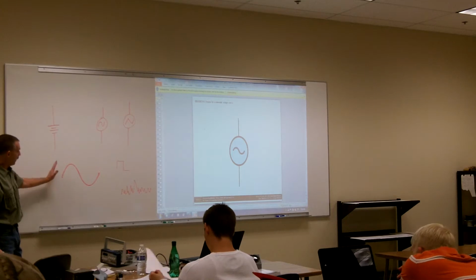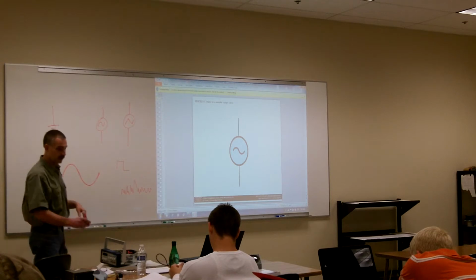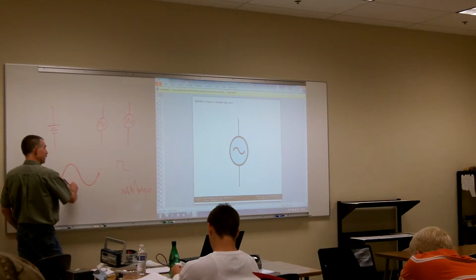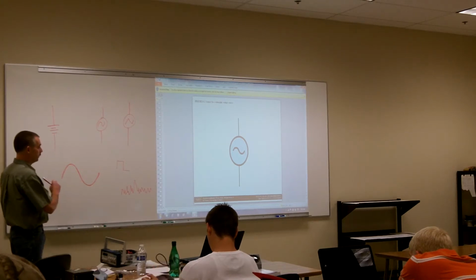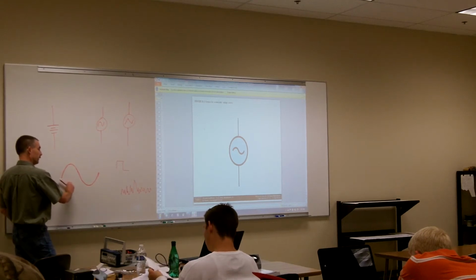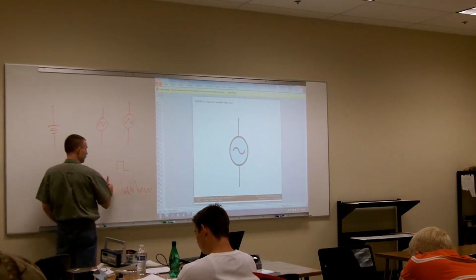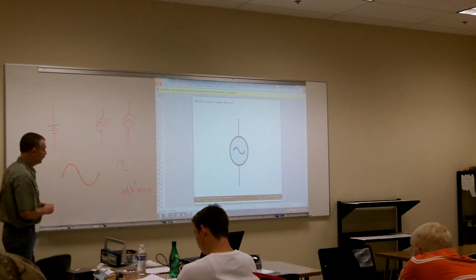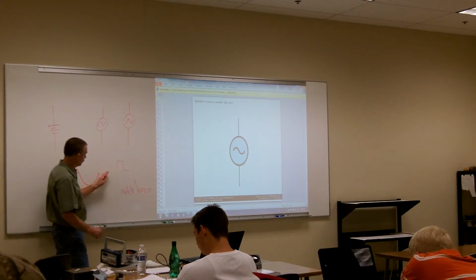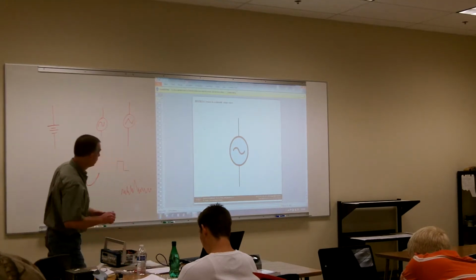So we can go from about 1 hertz or 10 hertz to 20 kilohertz, because that's the audible range of our hearing, and that's all the sound card's able to do. If we're doing something with audio amps or chips, that's what we call our frequency response, meaning that at 10 hertz I can get a nice signal, but after I get up into the higher frequencies, my components are going to have a low frequency response, and the signal is going to die after I go up past 20 kilohertz. But we'll get more into that as we go through the class here.